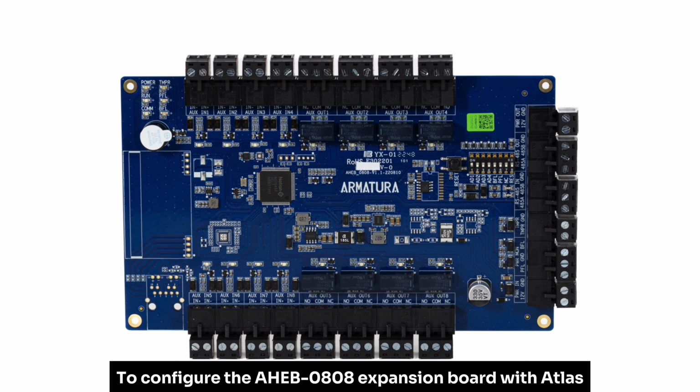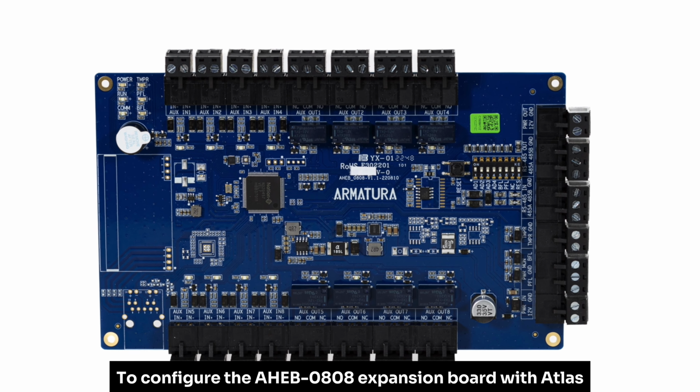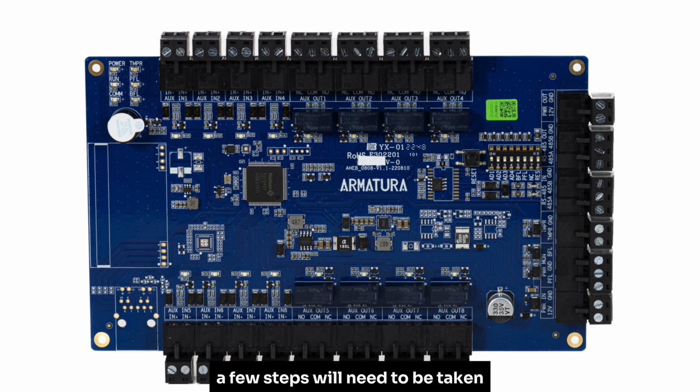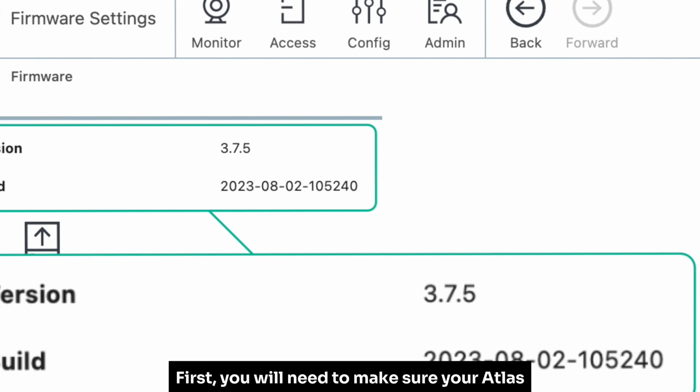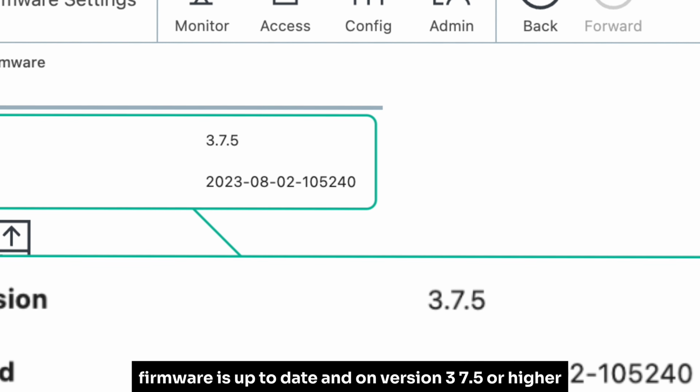To configure the AHEB-0808 OSDP expansion board with Atlas, a few steps will need to be taken. First, you will need to make sure your Atlas firmware is up to date and on version 3.7.5 or higher.